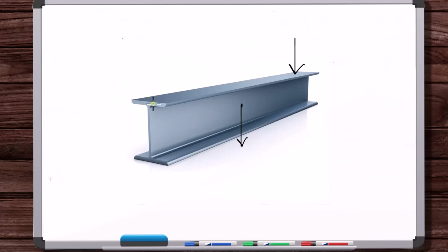Okay, so here's our cut surface. We have a point of contact here. We know there's some sort of load distribution here, but the contacting material right adjacent to this that we removed, what is that preventing the body from doing? Well, it's preventing the body from translating in the X, Y, or Z direction, and it's also preventing the body from rotating in any direction as well. It's a full constraint. It's constraining it from all types of rotation and all types of translation. That's the way you think about it.